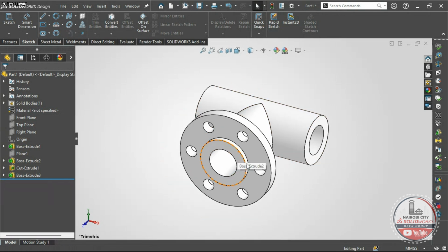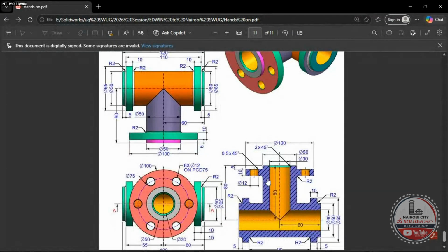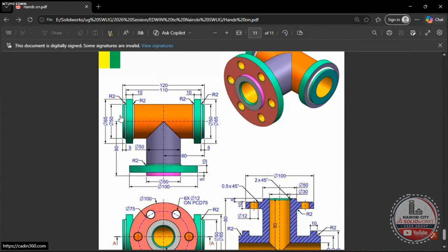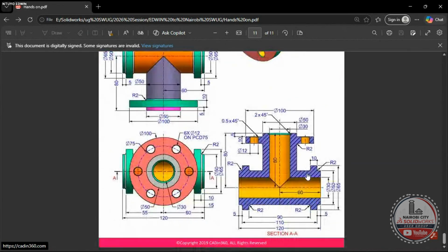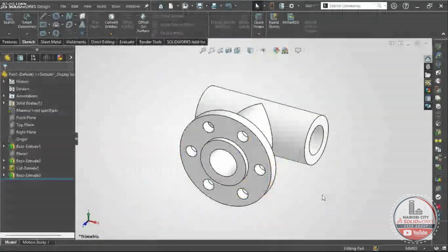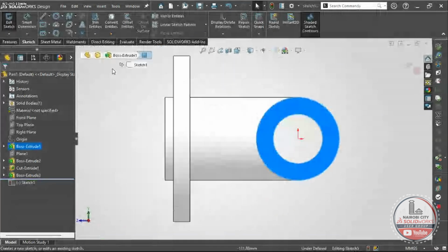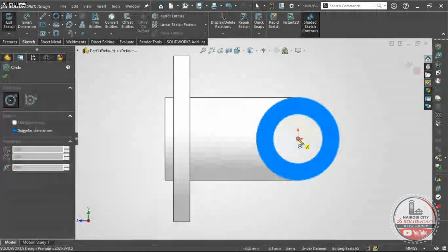So I have this at the moment, and you find that this is perfectly done. However, on these other opposite sides, I have the same thing. So when I come to the section, I'm going to draw there this angle where it goes for 65 diameter, and it is also offset a distance of 5 millimeters from the face. So when you come back, you just tap onto this face, you select sketch, it will automatically change, come to the sample, give in 65.